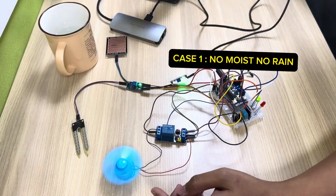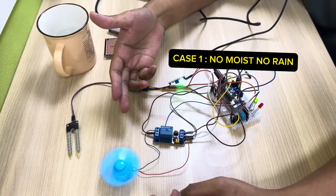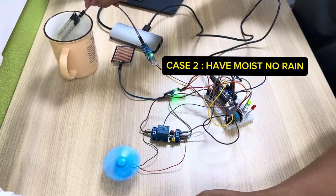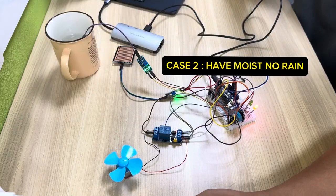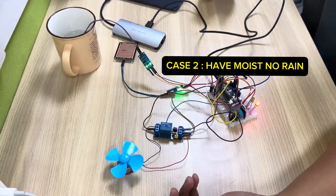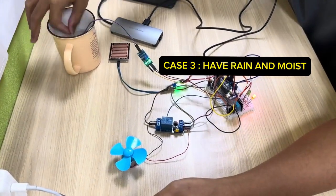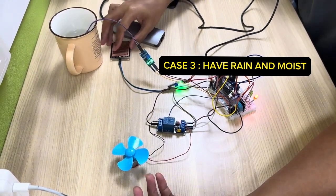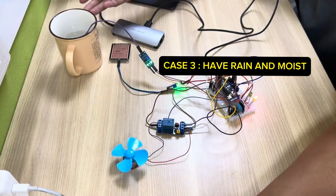Okay, so let's say it is not raining and the soil does not have moisture. You can see the sprinkler is currently running. The next condition is, let's say the soil has moisture and it is currently not raining. So the sprinkler will turn off and the LED will indicate red. The next condition is, if it is currently raining and the soil has moisture, then the sprinkler will not turn on, because the plants do not need the water.